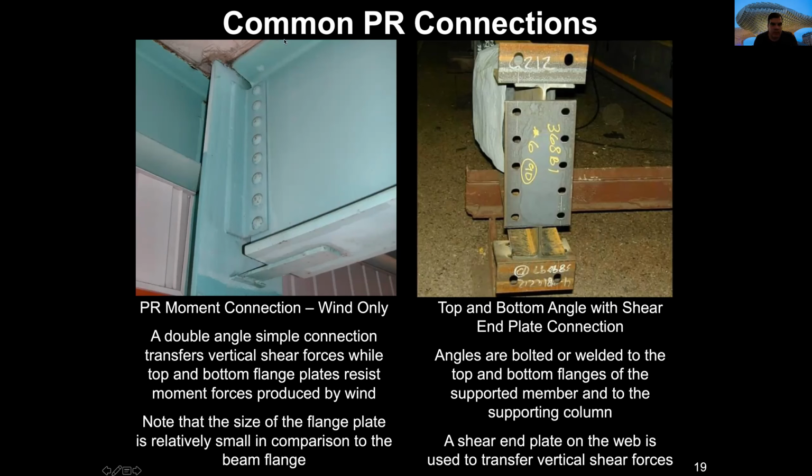That means that if we have a beam, and that is convenient when the beams are not so long, we have a beam and there are some forces there, and this is the column, for example, that is supporting that beam. Well, that will tend to have like a crack because it's short, it will not bend, but it will produce some shear. I mean, the possibilities to have some bending like that are not so big because the material is short, but there is a possibility that it will break here. Well, that shear connection will attach them in order to avoid that.